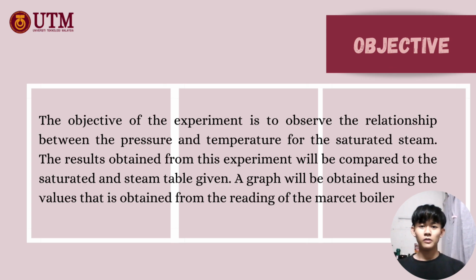The objective of this experiment is to observe the relationship between the pressure and temperature for the saturated steam. The result obtained from this experiment will be compared to the saturated steam table given. A graph will be obtained using the values obtained from the readings of the Marcet boiler.